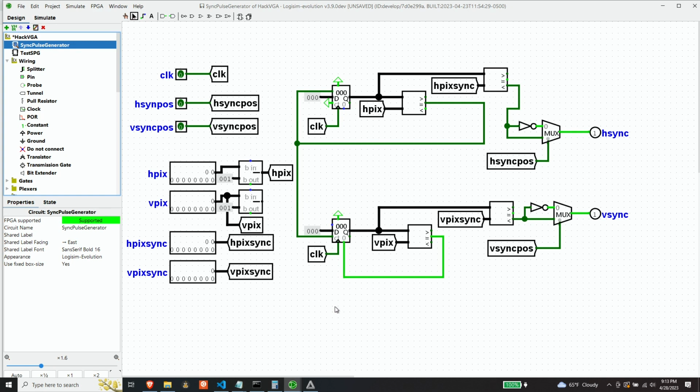And then the out of phase problem, this wire here was wired up to the load. However, once this is signaled, this gets incremented, this counter gets incremented, but it's not until the next clock cycle that it actually gets cleared. But once this increments and rolls over, we actually want this to immediately flip to 0, which would correspond to when the horizontal counter flips to 0. So those two changes now seem to make this work properly.